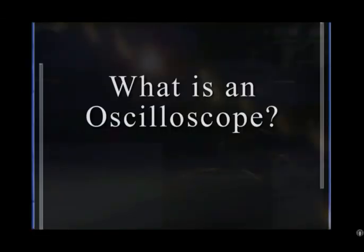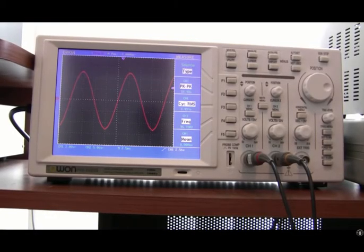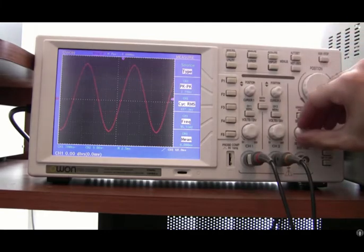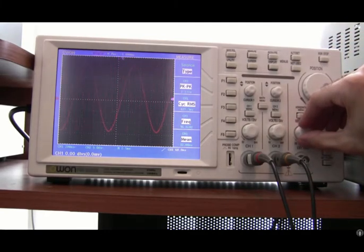First question, what's an oscilloscope? An oscilloscope is a device that lets you view changes in voltage over time. Volts go on the vertical axis and time goes on the horizontal axis. You can change the scales of the axes to measure tiny signals or large signals, fast-moving signals or slower signals.